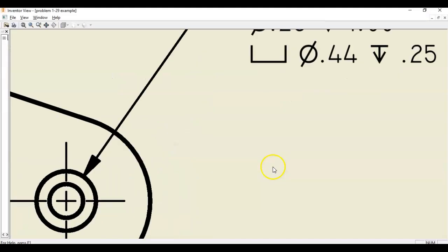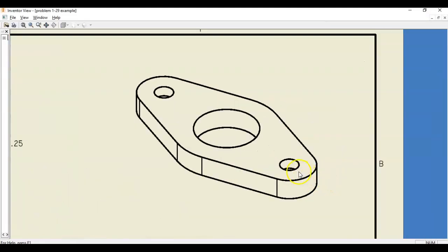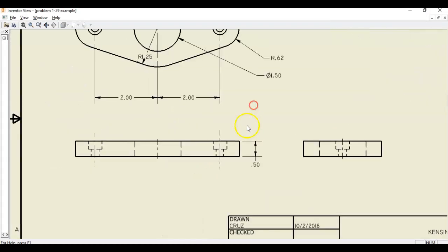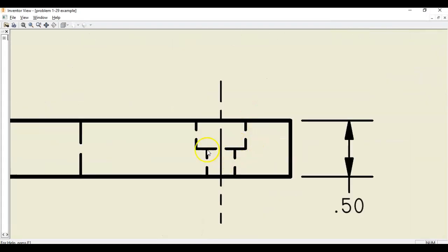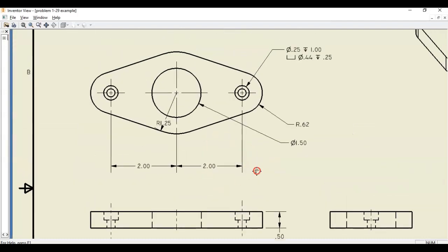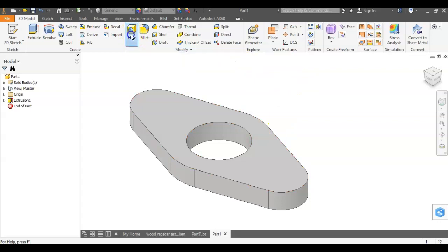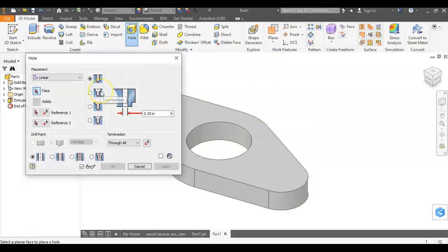So you'll see. So let's look at the ISO, see how it's not all the way down? And look at the inside of the part on the side view here, the front view. We see that it's not a hole all the way through. It's like halfway through with this wider diameter, and then the rest of the hole. So that's called a counterbore. Okay, counterbore.